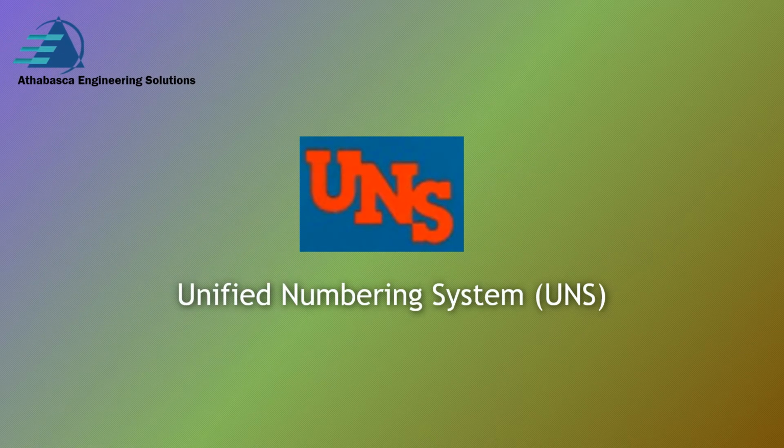Unified Numbering System, UNS for short, was a system developed based upon ASTM E527 and SAE J1086, about 50 years ago, 50 years plus, back in 1972. Basically, UNS allows a correlation of many nationally recognized numbering systems by societies, trades, and trade organization producers of metals, to avoid confusion, because there were so many materials that they were starting to get confused.